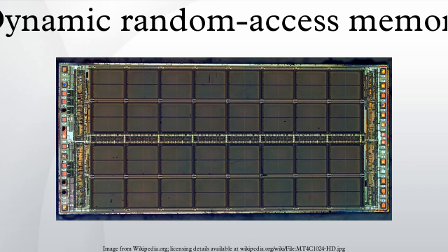Stacked versus non-stacked RAM modules. Stacked RAM modules contain 2 or more RAM chips stacked on top of each other. This allows large modules to be manufactured using cheaper low-density wafers. Stacked chip modules draw more power, and tend to run hotter than non-stacked modules. Stacked modules can be built using the older TSOP or the newer BGA-style IC chips.